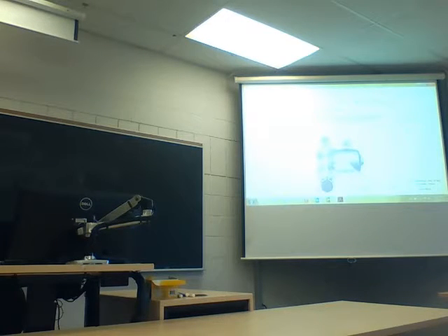Single stage centrifugal compressor having a volute casing with a single impeller, but no diffuser vanes. So they have them with diffuser vanes, the same idea as a pump, no different. This type of compressor is able to compress atmospheric air to a discharge of 350 kPa. Not very high pressure, is it? High capacity, low pressure. Absolutely. That's what they're designed for.